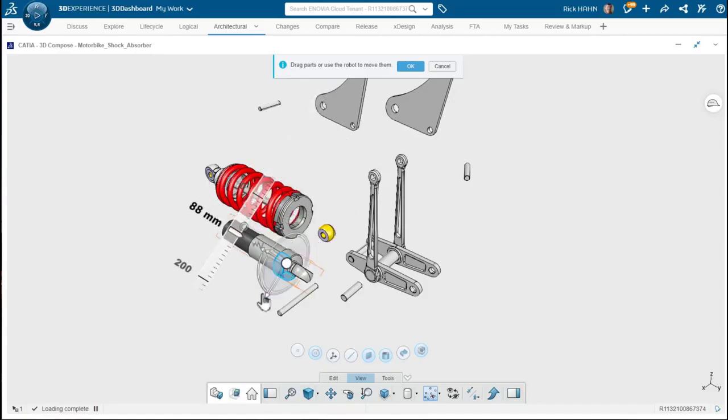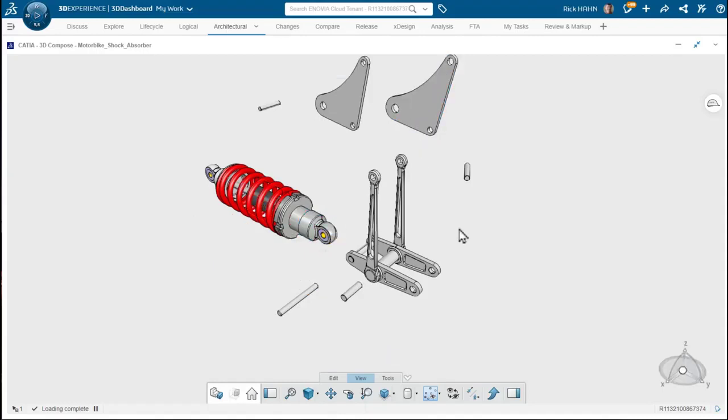But once again, we're dealing with discrete parts, which may not always be useful. This is where that third entity comes in, the selection group. When we select an element, you'll notice the orange outline box, which gives us an outline of what is defined in this group. We might want to change that and expand it. By selecting the selector here, we can work our way up the particular branch of an assembly tree and establish a better group.